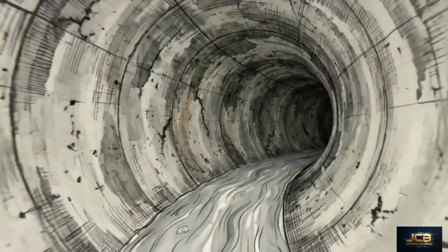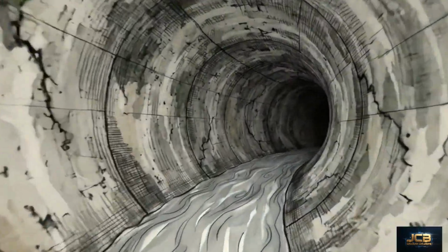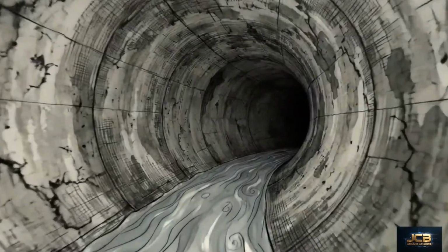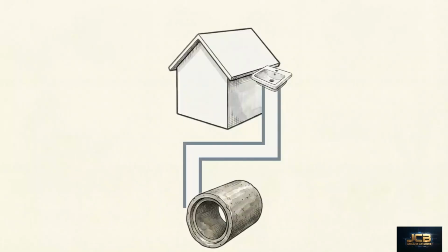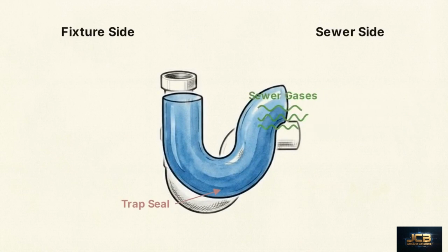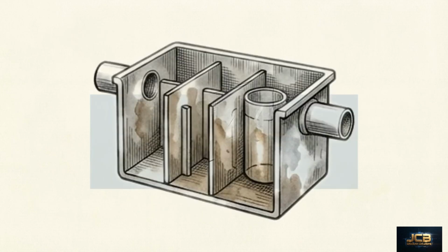A building's drainage network is a continuous pipe leading directly into the public sewer. Without mechanical intervention, this creates an open pathway for toxic methane gas to flow back indoors, and a channel for municipal infrastructure clogs. We secure this pathway using two strictly regulated mechanical devices. Traps act as the barrier against harmful gases. Interceptors, or clarifiers, defend against dense solids and coagulating oils.